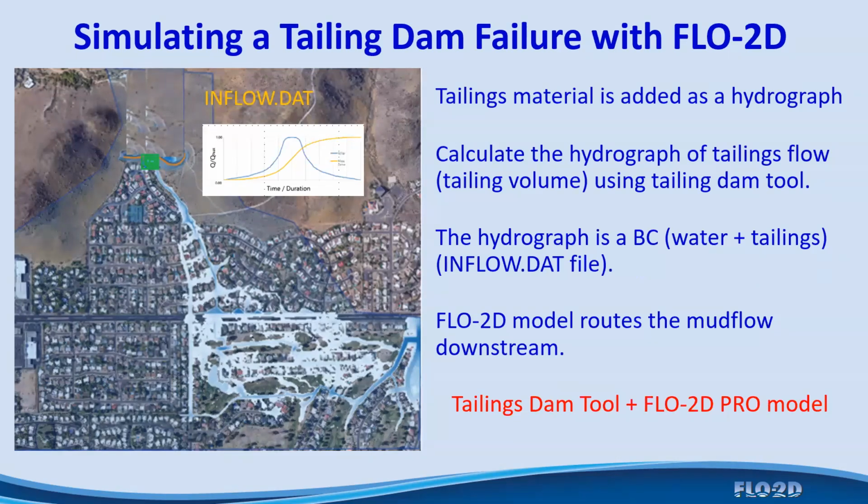You can also simulate a tailings dam failure using the Tailings Dam Tool and the FLO-2D model. The Tailings Dam Tool that I'm going to talk about today allows you to create an inflow hydrograph. So the tailings material is added to the FLO-2D model as a hydrograph.